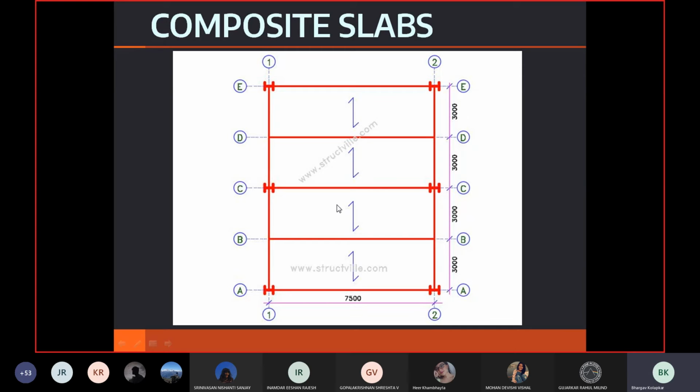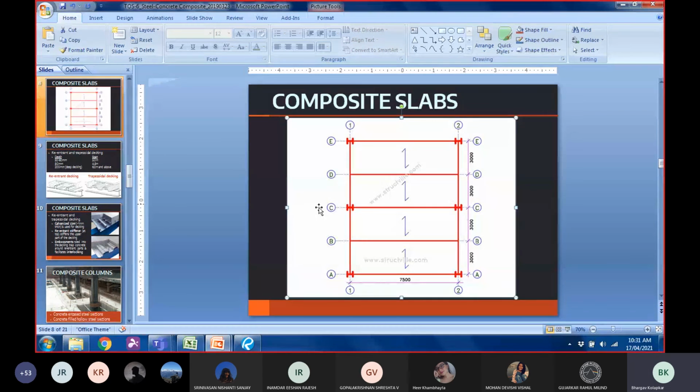Recently, we did a study when we were studying the possibility of a composite system for a mall that was planned to be built in Mumbai, and we extensively studied the system, and the thumb rule that we followed is there has to be a primary beam along the shorter direction. You can also do it the other way. Okay, I'll just tell you what I mean by this.